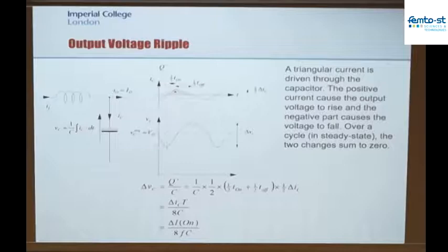In reality, we are going to see some change in voltage because that inductor is going to be a finite size, as is that capacitor. And in addition, as I mentioned, that is not going to be a perfect capacitor, so any additional current that goes into a series inductance or a series resistance in that device is going to give you some ripple voltage that you want to try and avoid.